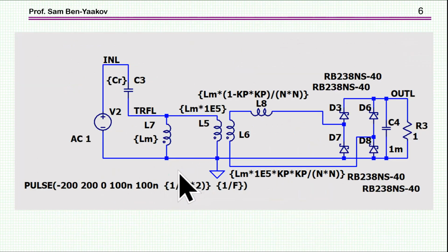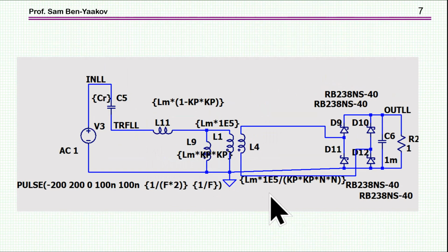And then I did a transformation and represented the same magnetic unit by this model, which has the parallel inductance here and the leakage here. So this is one of the options. I'm then representing another option in which the leakage inductance is here, Lm is also here, and here is just a winding of this ideal transformer. This is an ideal transformer.